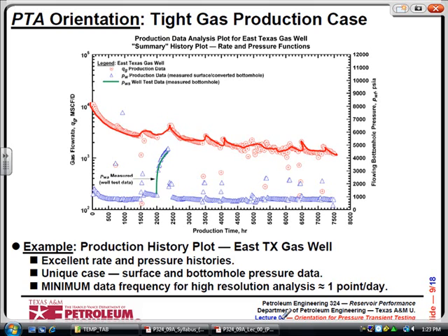And then this is a surface pressure profile converted to bottom hole. There's some jumps, especially where there were some zero rates. Now, I know you guys don't love this data set like I do, but you're going to. Anybody want to tell me what this is? So we have daily rates and pressures on a tight gas well. Absolutely magnificent data. What's the green thing?